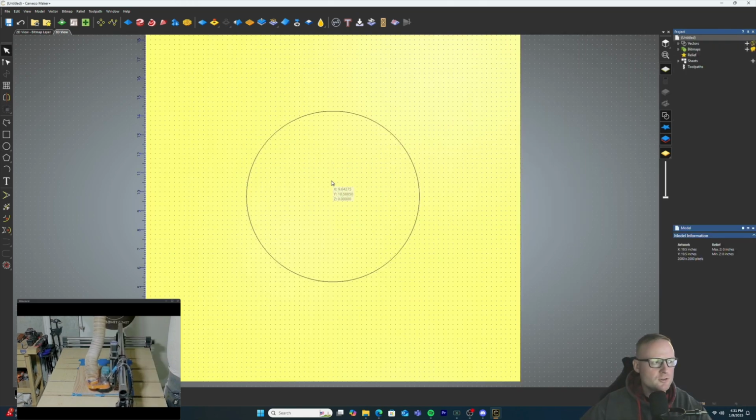Okay, so what we need to do next is create a series of vectors that we can manipulate using the Shape Editor tool. The Shape Editor tool requires all of the vectors that you use to be closed. So if you encounter any errors with that, make sure you're using Vector Doctor up here. That's a little bit more advanced. We can get into that if we encounter the error.